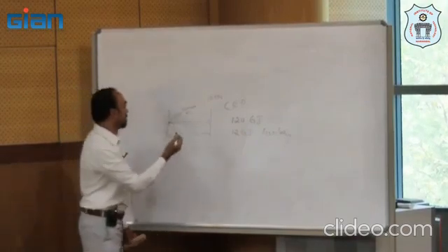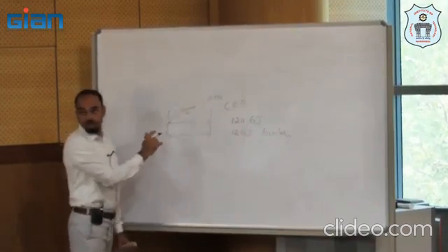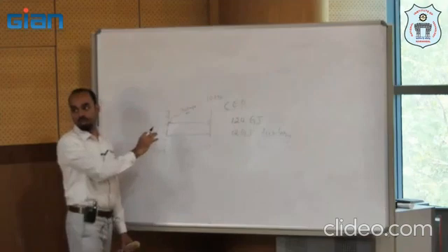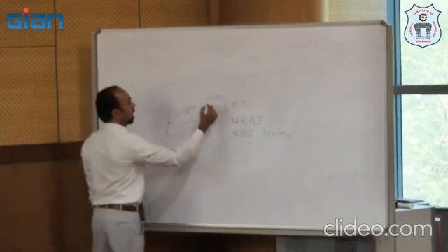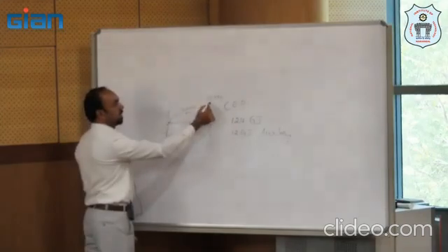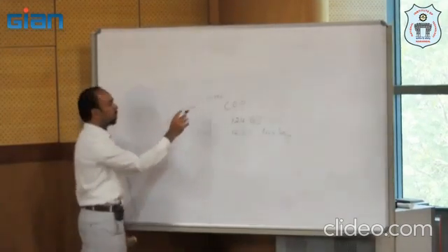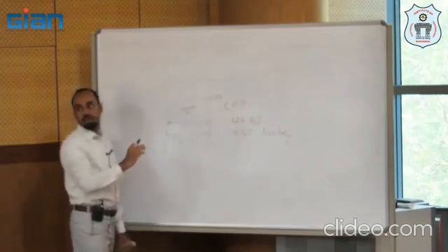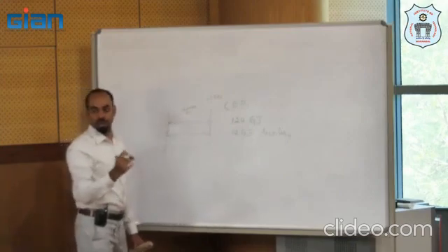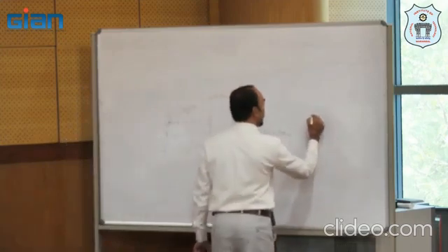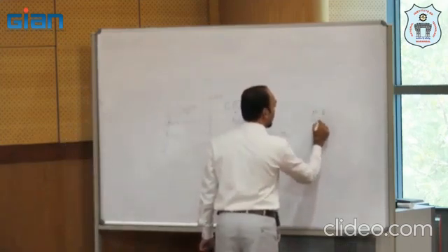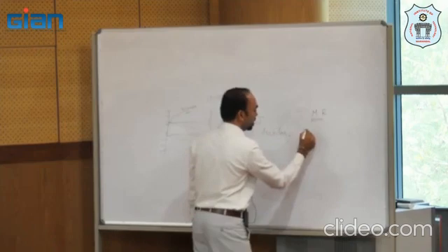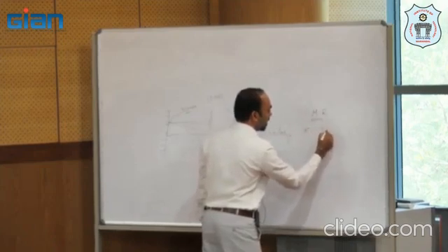So now the material is not selected. I am coming up with a material requirement for a given application. My application is to design a structure which will stand 10 kilonewton. To stand 10 kilonewton, I need a property with 320 MPa of yield. So I am deriving the material requirement. I will derive the yield, so this is 320 MPa.